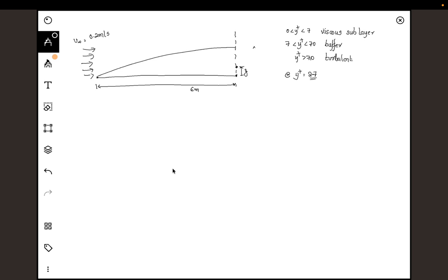The second part asks you to find this delta. And the last part asks you to find the average heat transfer coefficient. We will use the relations that we developed in the previous problem. We have the CF relation, we have the Colburn analogy, and from there we can calculate the Nusselt number. So the last part is straightforward. We already derived the average Nusselt number in the last problem. So you can use the same correlation, assuming that 3.5 into 10 power 5 is where the transition is happening.